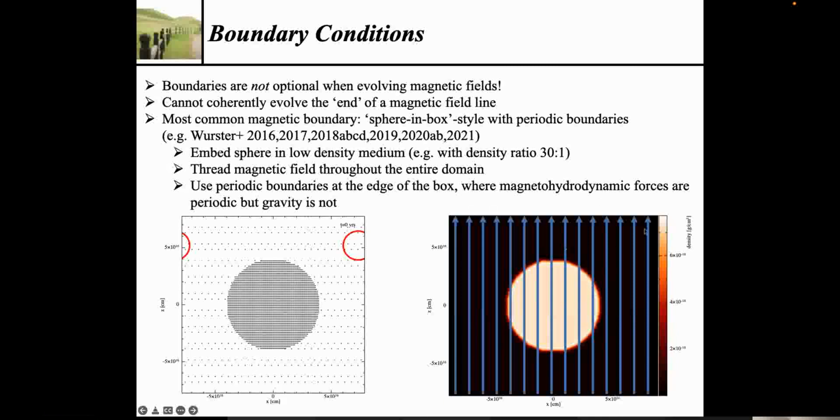So we no longer have an open magnetic field line, so we're satisfying physics and not causing numerical havoc. It also is a much simpler boundary condition to use. So this is one of the better methods to use if you need to model magnetic fields. If you're not modeling magnetic fields, then it should be safe to just ignore the background completely.